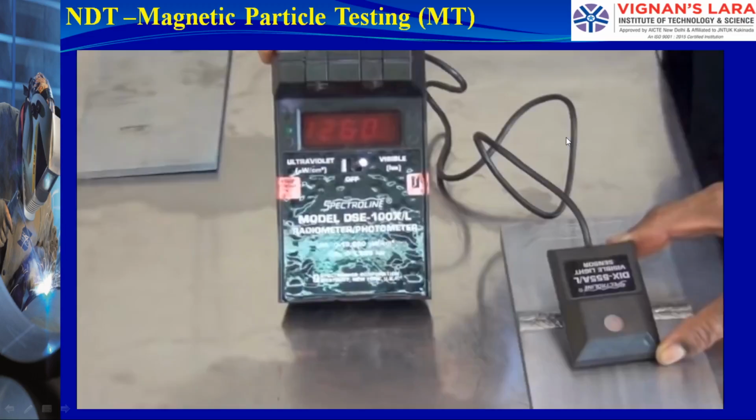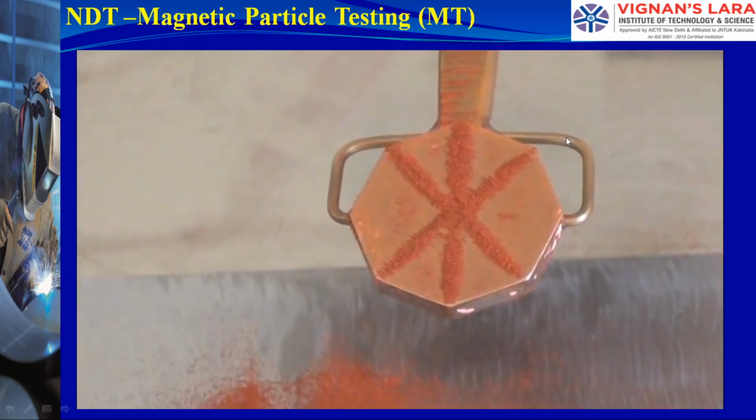The next step is to check the light level on the surface of the part being inspected. You can see that the light level is more than 1000 lux, and that is acceptable. Here we check the magnetic flux intensity or adequacy using a pie gauge. Here we go, and you can see very clearly that the lines which are normal and at 45 degrees to the magnetic flux are very clear, and the line that is parallel to the magnetic field is not visible.